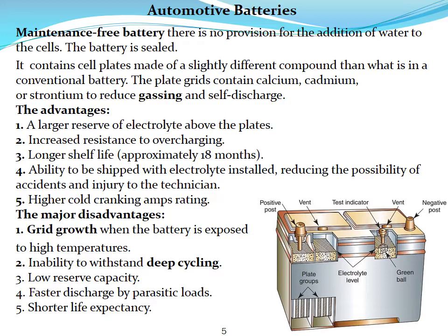Higher cold cranking and power rating. The major disadvantages: first, grid growth when the battery is exposed to high temperature, inability to withstand deep cycling, low reserve capacity, faster discharge by parasitic loads, and shorter life expectancy.